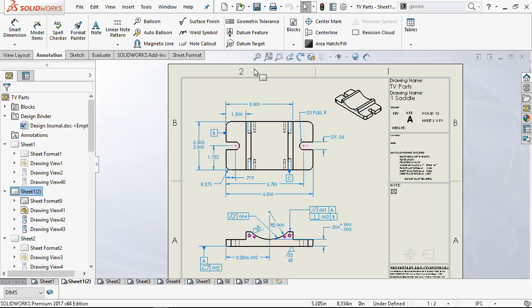Well, industry says that this all needs to be plus or minus half a thou. Like we just said earlier, we've doubled or tripled the cost of this part for a slot that in no way, shape, or form, 0.56, needs to be 0.5600. All right? The critical dimensions in these areas, yes. Everything else, not so much.